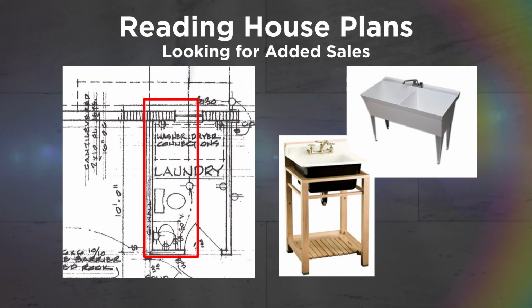This wet wall has a lot on it, with plumbing, both supply lines as well as drain waste vent lines packed into this short wall. A wash station in the garage would certainly keep the rest of the house much cleaner, particularly for a person that loves to work outside or in the garage. Everything we need to plumb a sink is found in this common wall.